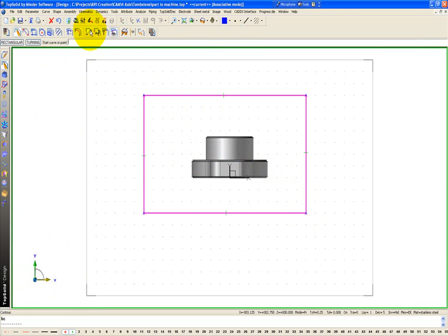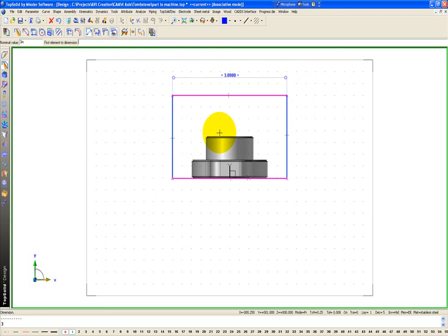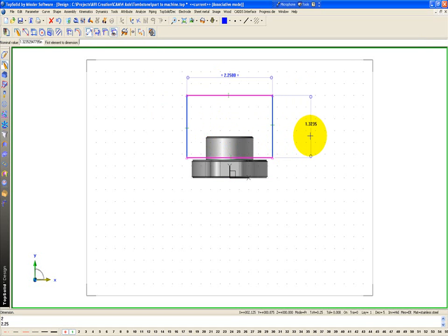And what I want to do here is this. I'm going to add a dimension here. After I've located the dimension, I'm going to select it, go to Constraint, choose the Y-axis. And then I can play with this. I want a 3-inch standard, a 2-inch standard, how about a 2 1/4 inch piece of material? Okay? Now what I want to do is define the standard thickness I need.